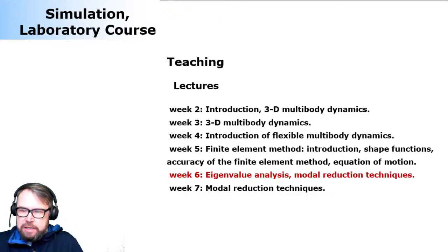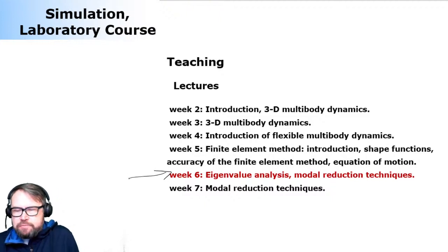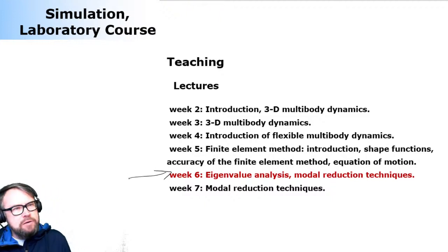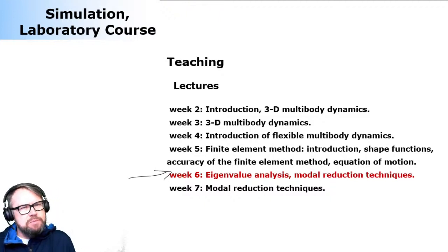Okay, so eigenvalue analysis and then modal reduction. Those two are kind of like brothers, because we do need both. We do need eigenvalue analysis to conduct the modal reduction. Although there are other techniques to carry out the modal reduction, other than the ones that are based on eigenvalue analysis, many are, one way or another, based on eigenvalue analysis.